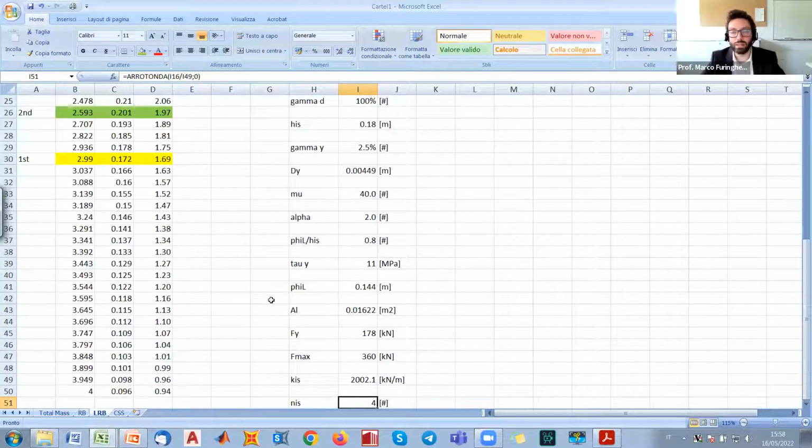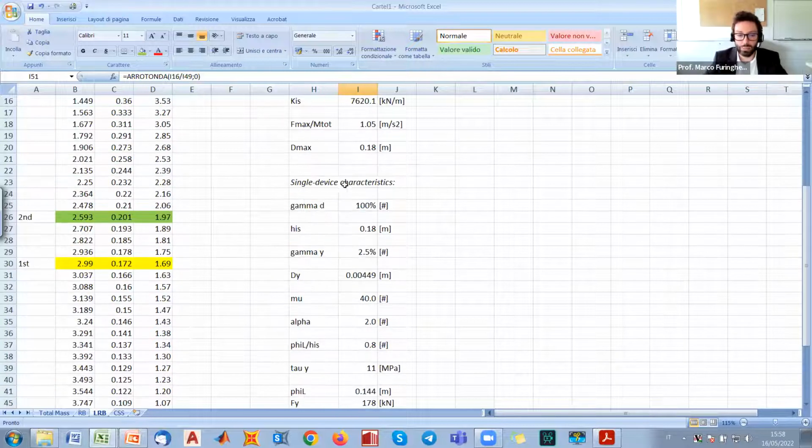Tomorrow we will come up with the definition of the seismic input, to carry out non-linear time history analysis according to a selection of 7 natural earthquakes. Then we will perform the analysis on Wednesday, and compare the average results among the selected events to the numerical values of the performance that we have computed here for pre-design.